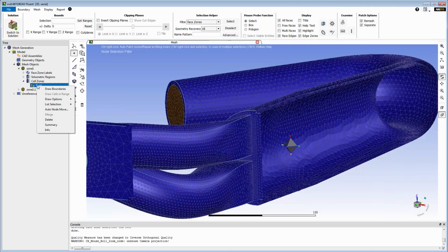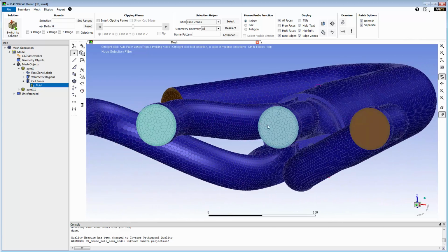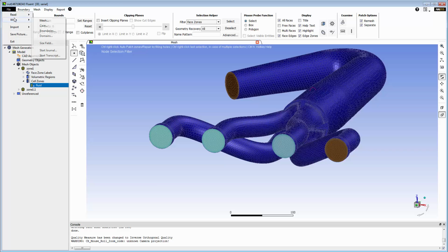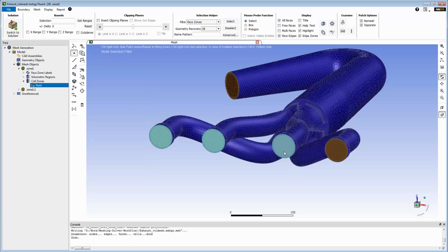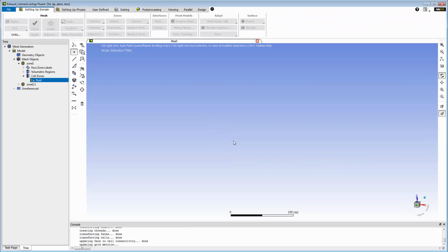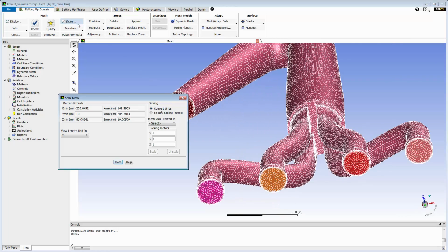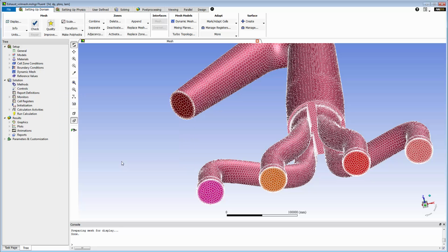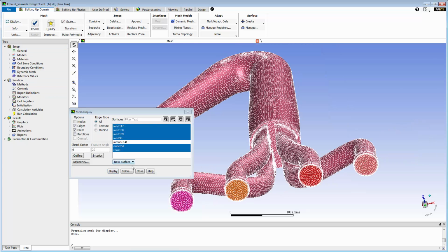Once the mesh is generated, I can preview it. By looking at the external boundaries, I can see that nice polyhedral elements have been created. I'll save the mesh file and then change to the solver mode in Fluent by clicking the Switch to Solution button. Fluent assumes meters for all length units. I'll select millimeters to scale the mesh. After scaling, I'll redisplay the mesh to make sure that everything looks as intended.